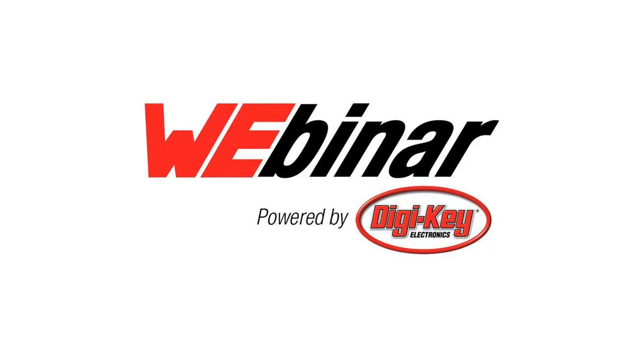Our next question here: do you see many real applications using USB 3.0 with PPS? I believe that this might go to Jeff, but Jeff, you can correct me if I'm wrong. Sure. Yeah, so with PPS, the programmable power supply, and the name of that spec from Qualcomm and their branded version escapes me now. I think it's Quick Charge. We do see that happen. That's really more on the source side, I believe, where we would have to pass through a different voltage on the VBUS. But yes, the short answer is we do support PPS.